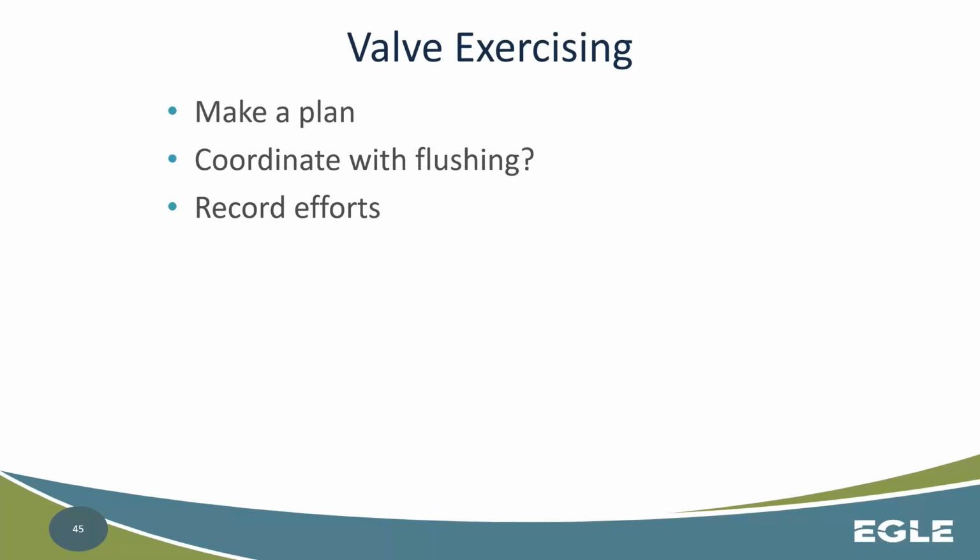And if you are isolating portions of the system while exercising, maybe you're doing those in the middle of the night when water usage is low, or you're advising the customers on that leg, hey, you might have a moment here where you're not going to have as much water pressure as I do this. So if you could just avoid using the water while I exercise this valve for the next half hour or hour, that would be appreciated, kind of thing. So making a plan is very important.